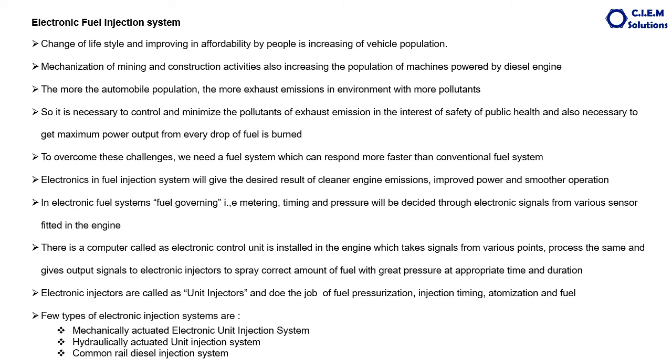So what are the advantages of the electronic fuel system? I am going to tell you. The advantages are faster response to the load variations on the engine. The ECU operates at almost 60 times per second and even more. I told you, some ECMs are designed to respond every 2 milliseconds. The ECU decides the fuel quantity based on various inputs from the engine, unlike the simple mechanical governor in the conventional system. Higher injection pressure, better fuel atomization.